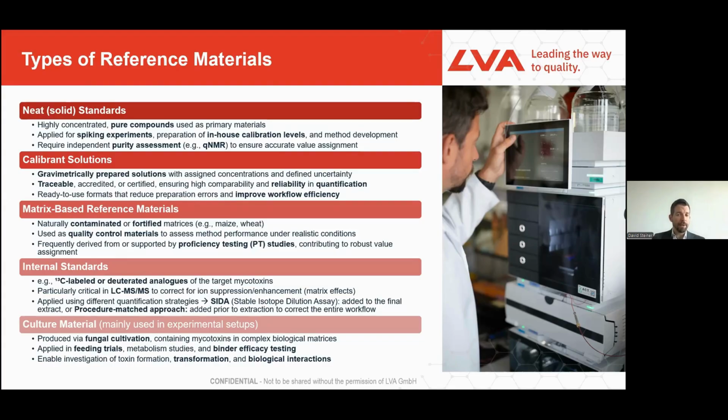Then we have calibration solutions. These are usually gravimetrically prepared and come with assigned concentrations and also a defined uncertainty. And because of their traceability, they are essential for an accurate and comparable quantification.